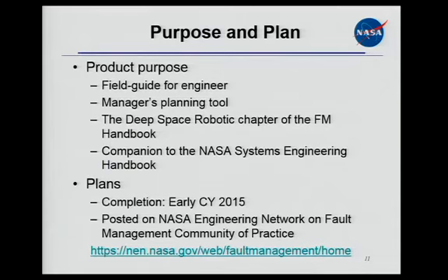I'm glad you mentioned model-based. I would actually love to see this field move in a model-based direction. So the field right now, I think of as a field of Band-Aids. So you've got your nominal design, and then you think about, oh, if this fault happens, then do that. If this fault happens, then do that. And you can think about all these monitors, these if-thens, as a set of Band-Aids. And that's why when you get into integration and test, you end up with a bucket full of Band-Aids that's really hard to test because they can interact with one another and overlay one another and interrupt one another.